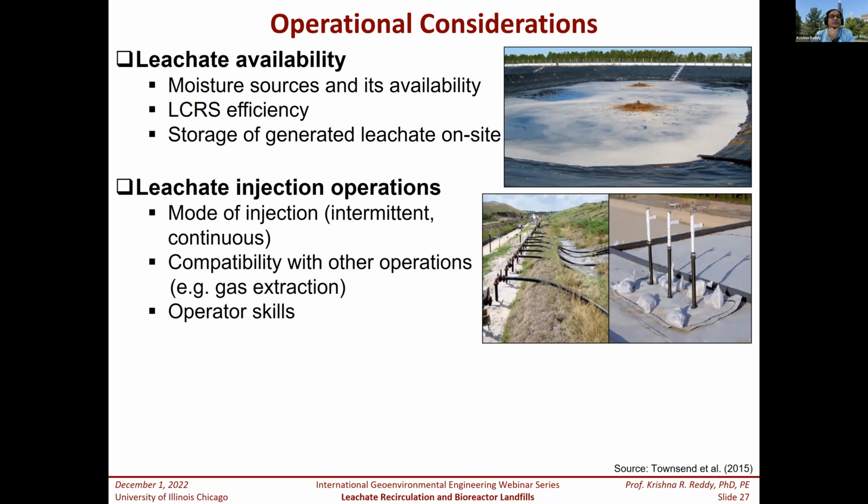Leachate injection operations. Leachate can be injected continuously or intermittently. And remember, if you have a landfill with a large area and a lot of these leachate recirculation systems, wells, or trenches, you may not have a lot of leachate to put into every leachate recirculation well or trench.